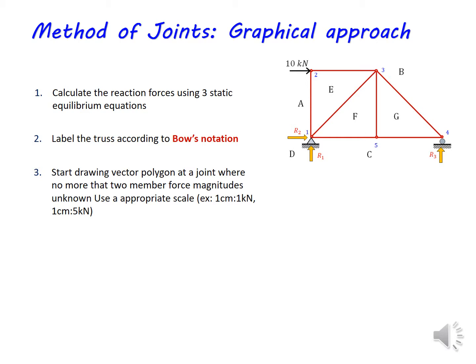One more thing, when drawing the force polygon or the vector polygon, we should select an appropriate scale. For example, I can use 1 centimeter to represent 2 kilonewton. And we should mention what scale we are using when drawing to a scale. So I'll start drawing the vector polygon, and I select joint 2 to start with.